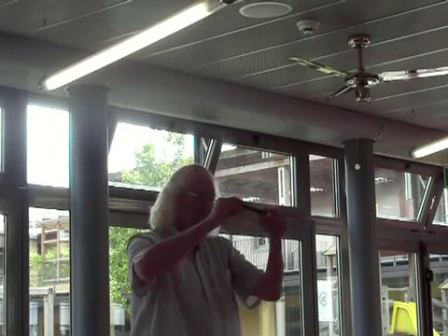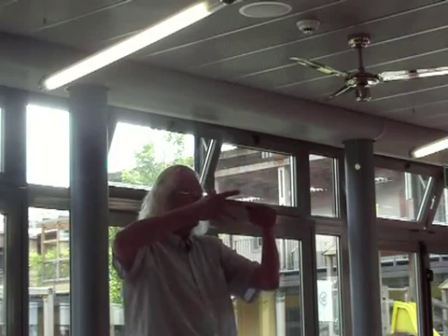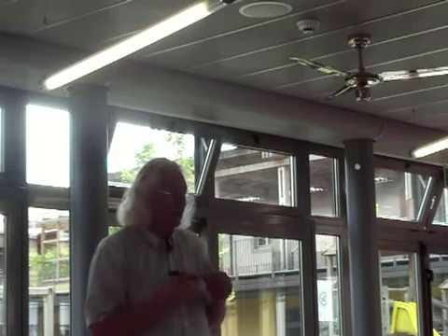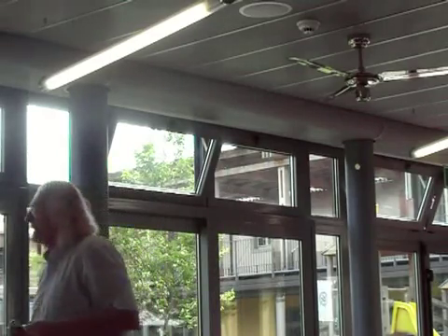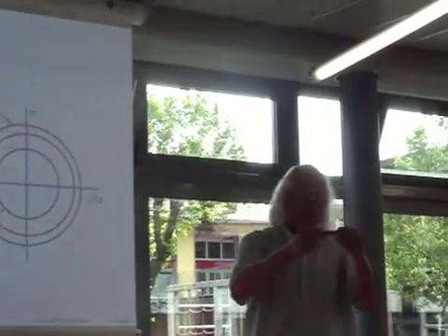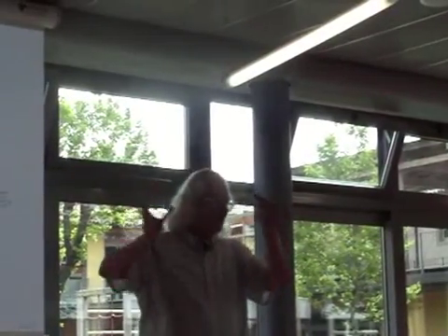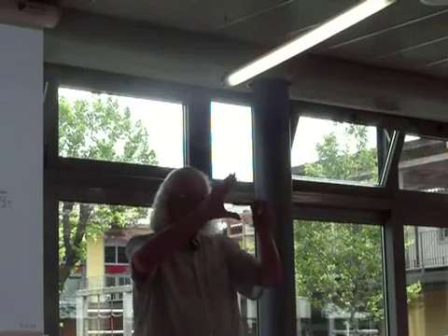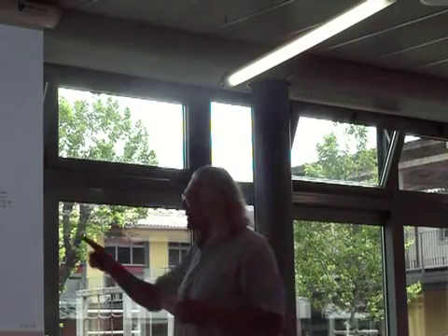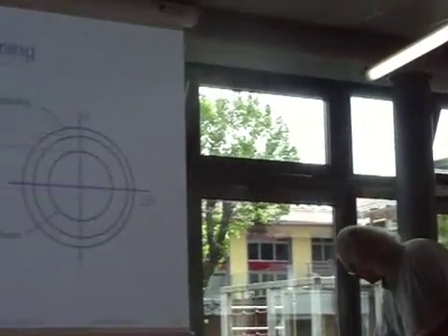Right? And I could have twisted it in torsion first, and if I strengthened it in torsion, it would also be stronger in tension. And that's this idea of isotropic hardening. It hardens everywhere in it. And of course, the material determines the rate of hardening and the final saturation, and things like that. But all materials will have some initial hardening to it.